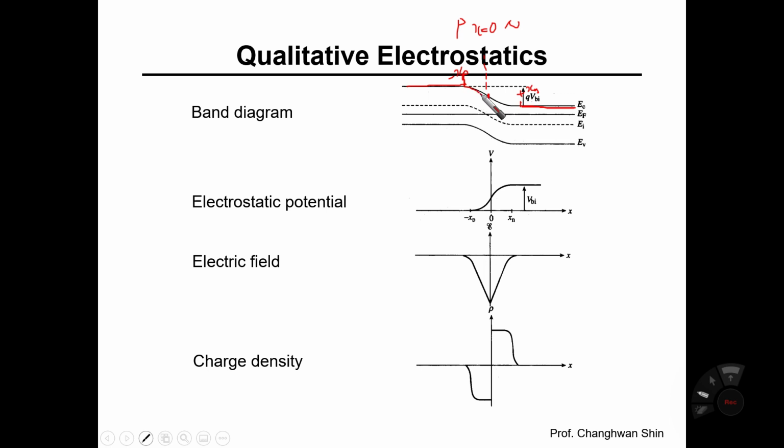And the conduction band edge follows a second order equation, so a parabolic shape. And another second order equation, so a parabolic shape, should be used when you draw the energy band diagram. So you have some experience. Please draw the energy band diagram across the Pn diode. Then many students are doing this. This is wrong. You should watch out.